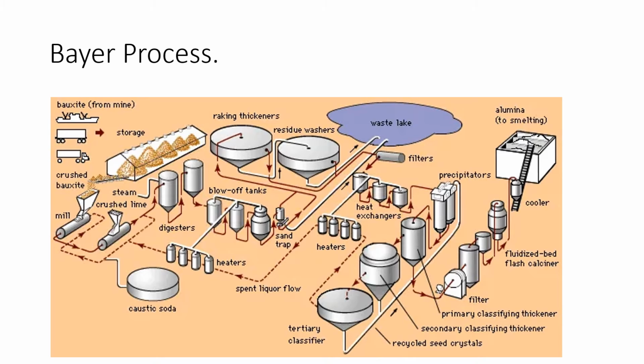Free water and chemically combined water are driven off, leaving commercially pure alumina, or aluminum oxide, a dry, fine white powder similar to sugar in appearance and consistency. It is half aluminum and half oxygen by weight, bonded so firmly that neither chemical nor heat alone can separate them.